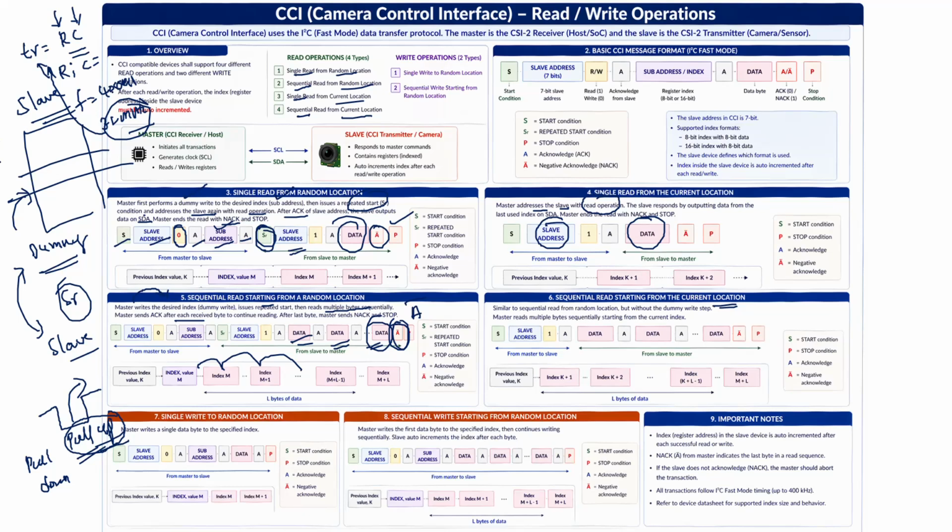There is another component, the pull-up resistors. The RP values will keep that SDA line from low to high. Then only the next master will know that the SDA line is in idle condition, then it will be accessed.